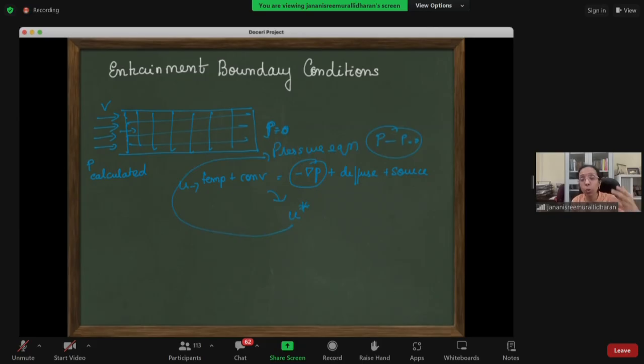Now, what if I don't know the velocity at the inlet? Then say I know the pressure. For now, I know the pressure, so there is a P1. Let me get into the iteration now. I have no clue what the velocity is, correct? So when I have no clue what the velocity is, I'm going to assume a velocity. So your u prime is there. But when I go into my continuity equation, I have P fixed on every side. So the numerical stability cannot be there because my initial u is going to be significantly wrong.